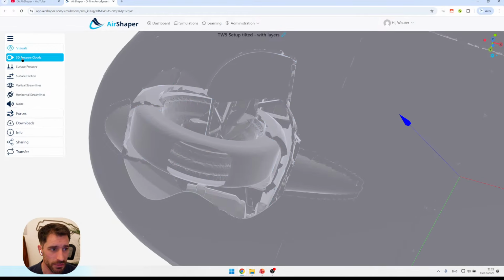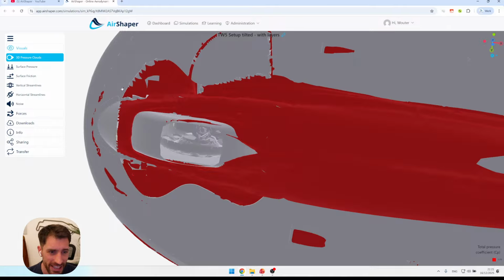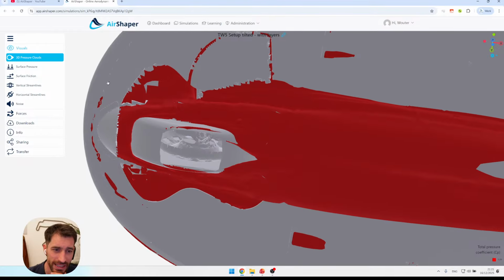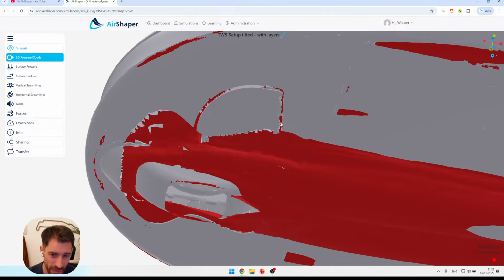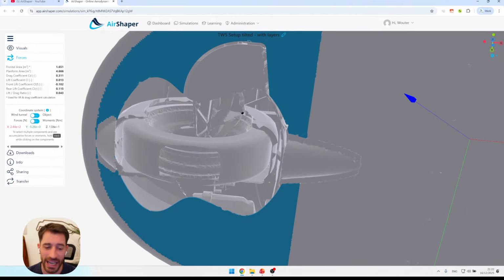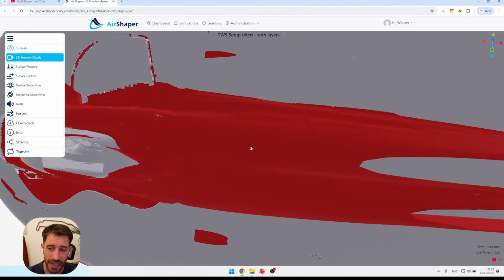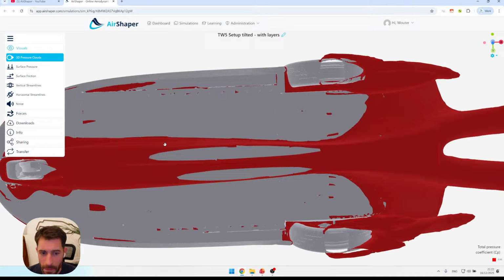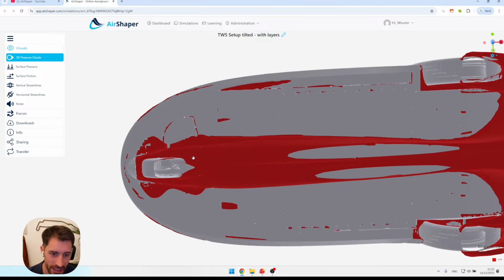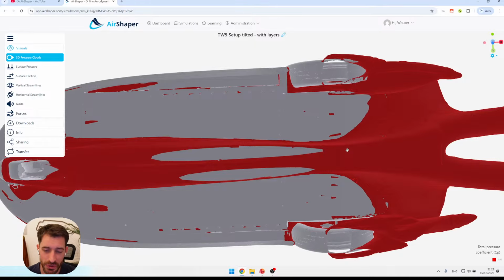So what we saw in terms of flow results is that as soon as the air hits the edge here, it separates, because there's no way that the air can just curve inside and follow the curvature. It separates, it has to jump this gap, then hits this suspension. We call it a single-sided suspension element, because the wheel is suspended from one side. It hits that element, then again comes across the gap here, and again hits the end of the gap, and again separates. And this translated into a very significant wake, traveling all the way downstream, not just causing drag on the wheel itself, but causing a lot of problems in the diffuser as well.